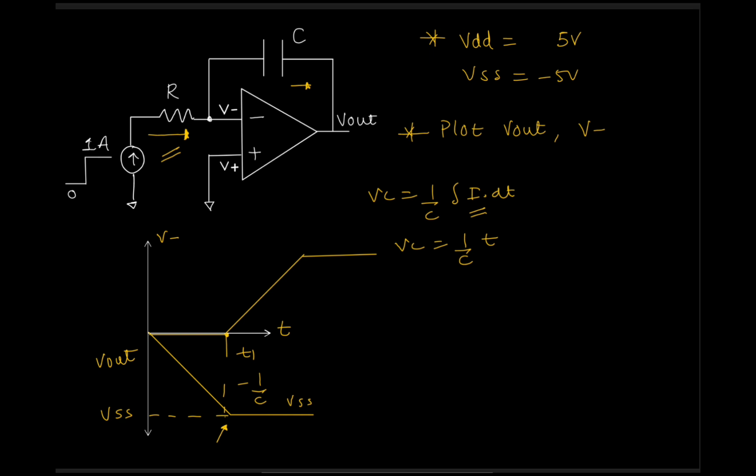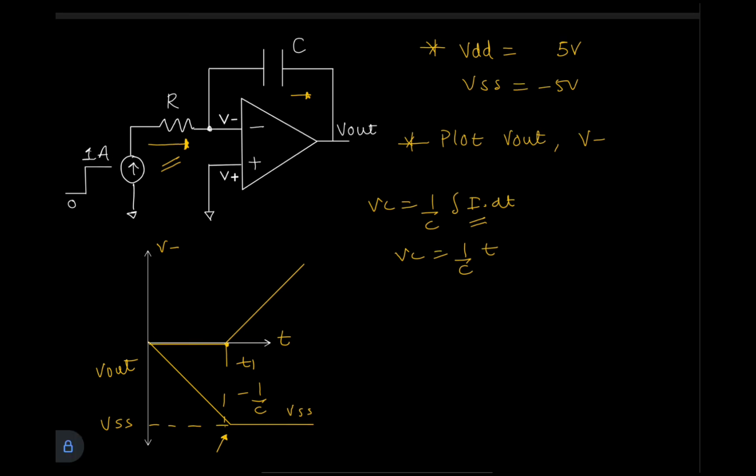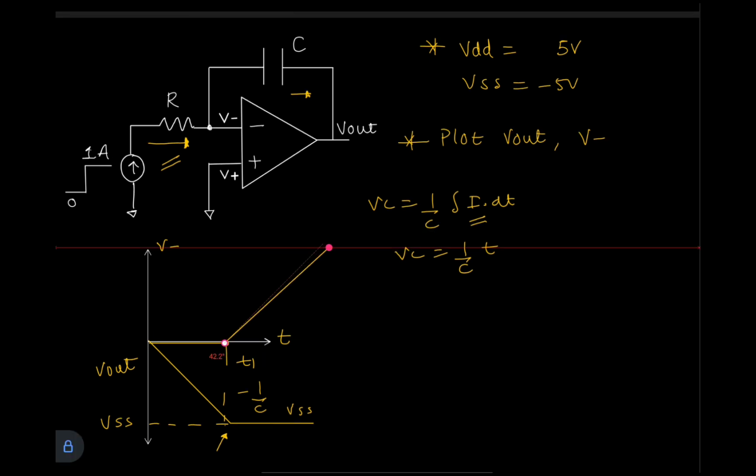Okay, no, sorry, this will not settle, because at that point this voltage was settling since the current was getting constant, but here we have a constant current source. The current will not be 0, so it will keep increasing. They also asked me, is there any limit for this voltage? I told them there is no limit. The only limit it can have is the limit of what the current source can supply, and they said it is an ideal source, so there is no limit.